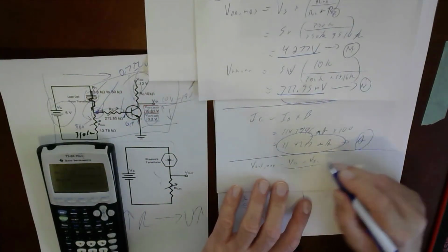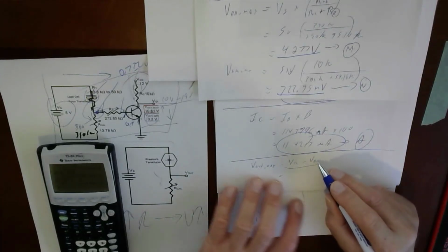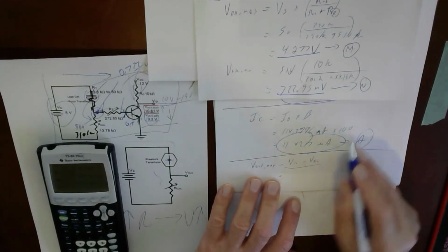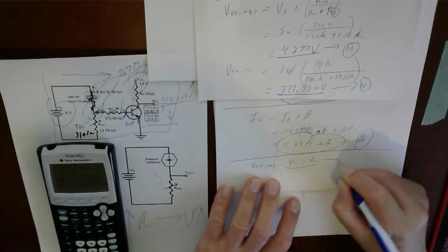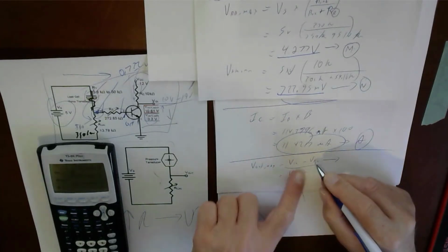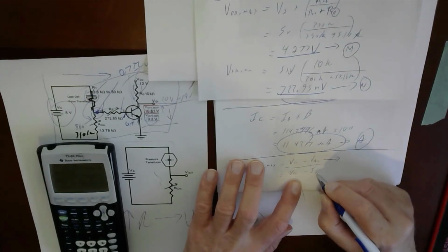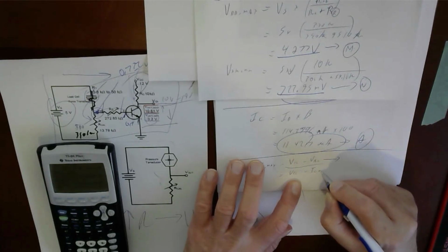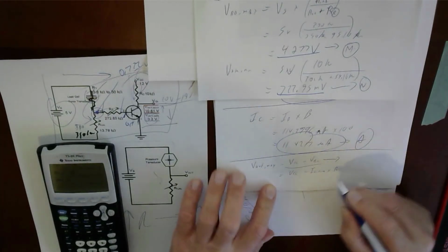So I am just going to do that, and then I'm going to calculate this guy by multiplying this times the resistance. So VCC is actually, let me just rewrite this formula again. I'll write it down here. VCC minus, to calculate VRC, I'm going to say IC minimum times RC.